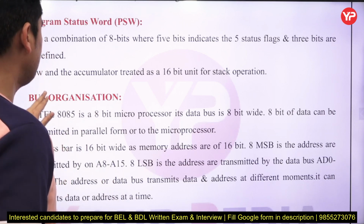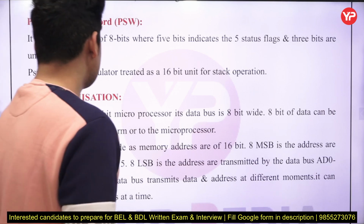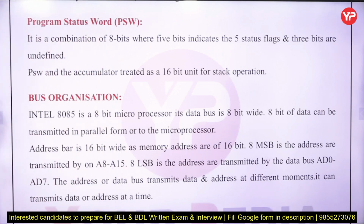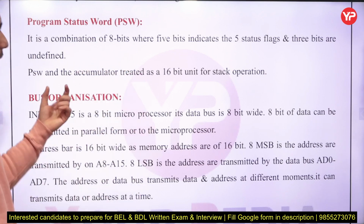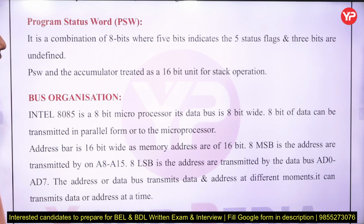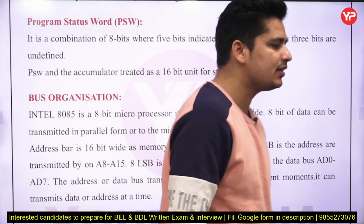Program status word. This is a special type of register inside your microprocessor. It is a combination of 8 bits, where 5 bits indicate the status of 5 flags, and 3 bits are undefined. PSW and accumulator combined act as a 16-bit unit.